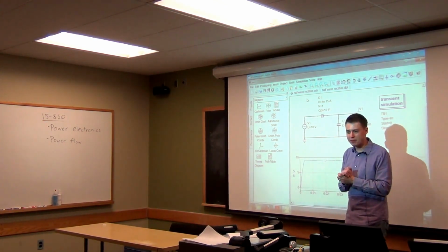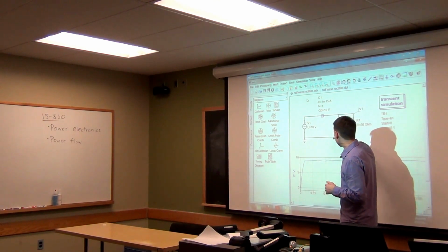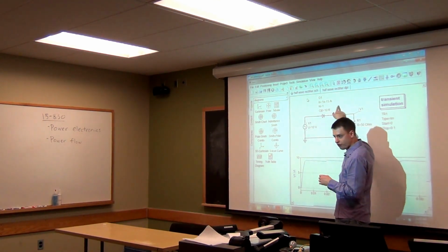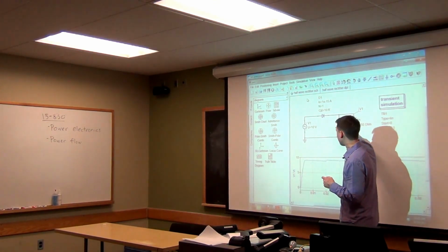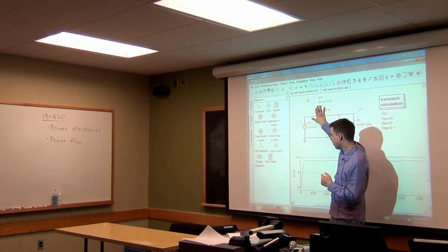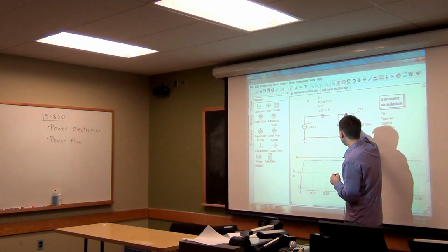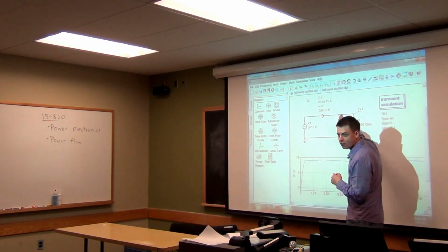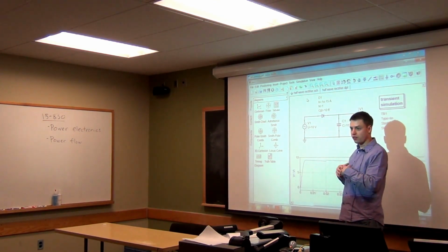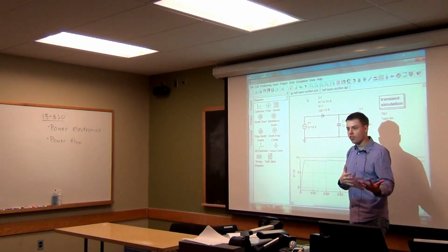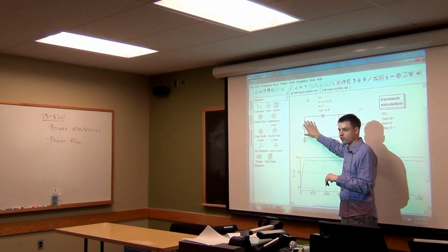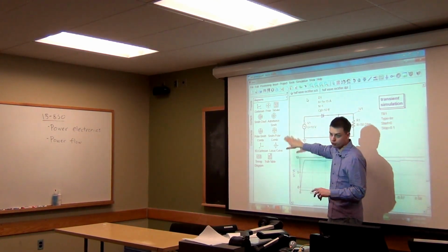Okay, so what's happening here? What's happening is that this capacitor, when current is flowing around here, it flows through the resistor here, but also builds up a charge on this plate here. Then when we shut this off, so it's trying to flow the other way, we can still have current flow around this way, because this has built up positive charge and this has built up negative charge. So the capacitor will store this energy and provide it to the resistor when this rectifier is blocking the actual voltage source from providing energy.